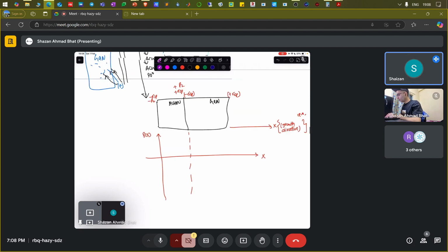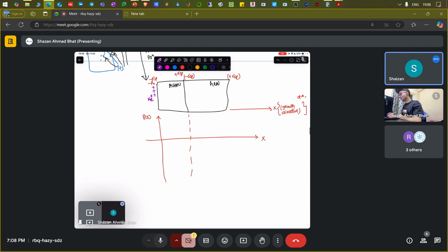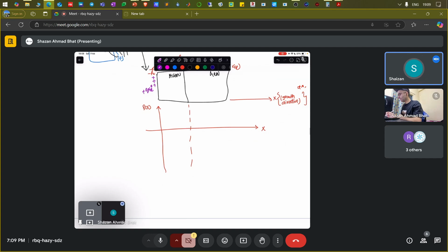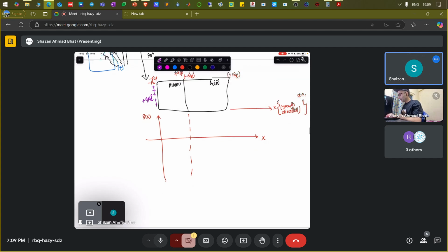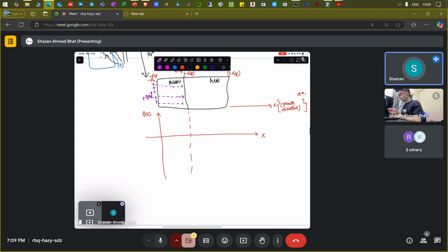So overall, now what you see, and also you have positive donors. Let's call them ND, N and small d, and capital D over it. It's not just like a doping. These are donors which are positively charged, just like a plus Q times Nd. These come from the surface states. And why are they positive? Because the electrons have left here and they have settled at this particular region. Now you have to draw the charges, just the charges.